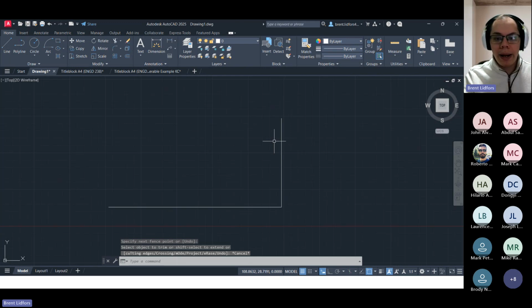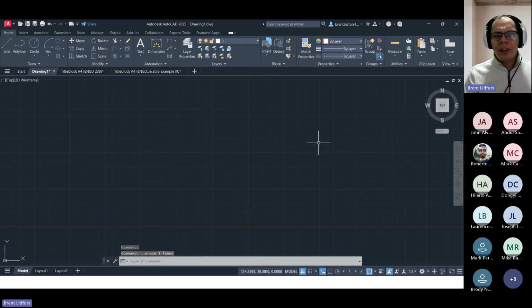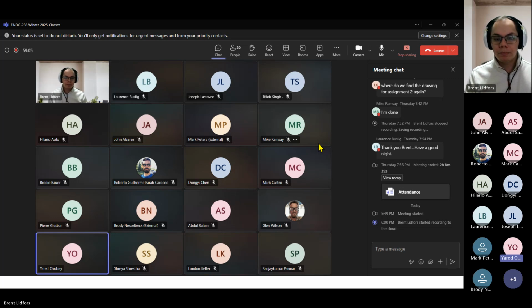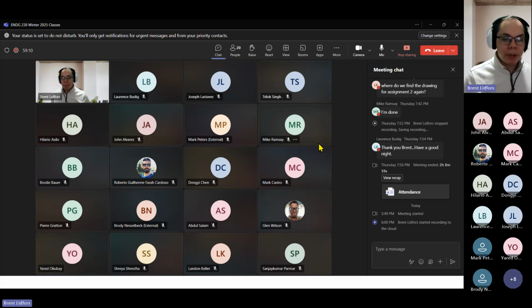So you might have noticed right away, but what's the difference then between trim and erase? They're both removing lines or removing shapes from my drawing. What's the difference between trim and erase? Don't they do the same thing? Anyone know? I think erase the whole rectangle, but trim can erase parts of the rectangle like lines or sides. That's what I noticed. Yep, exactly.